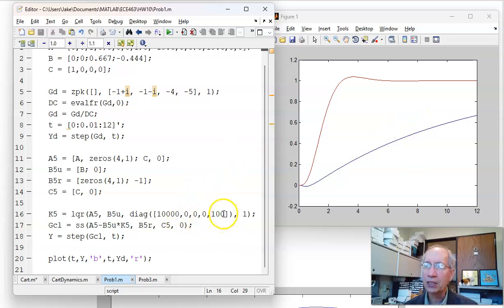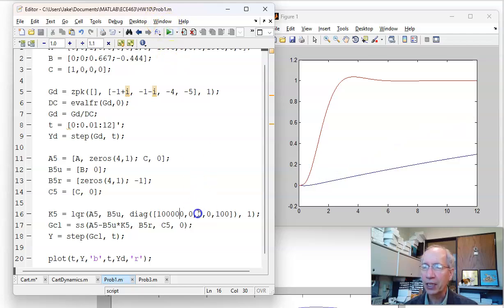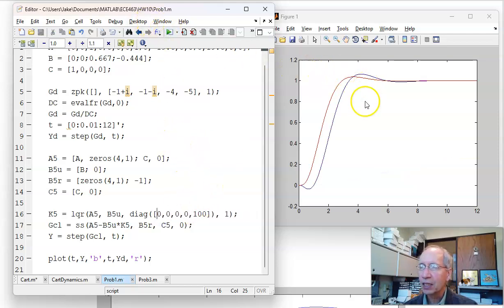The control law is dumb. It thinks that Z is the output. It thinks that Y, this right here, is the derivative of the output. So the heavier I weight the derivative, the slower I get. So again, I don't actually want to weight the derivative, get the desired response. Here I might have too much overshoot.